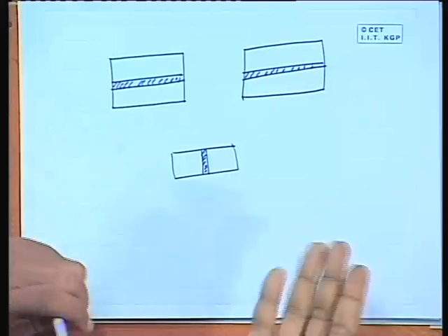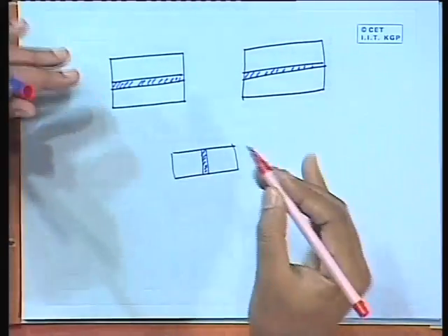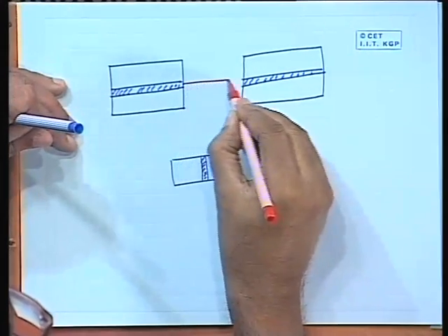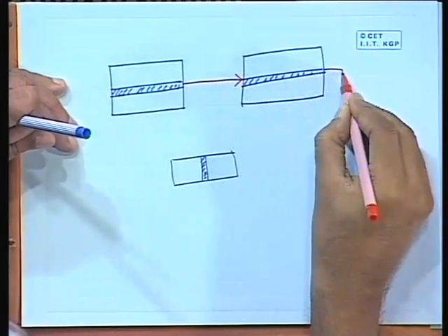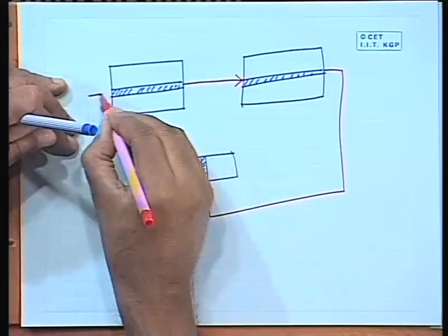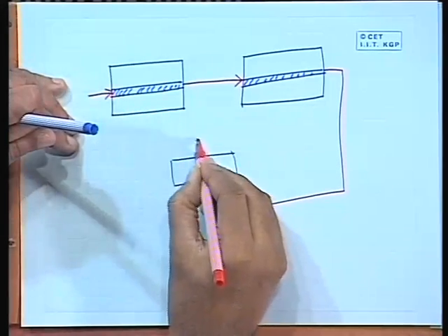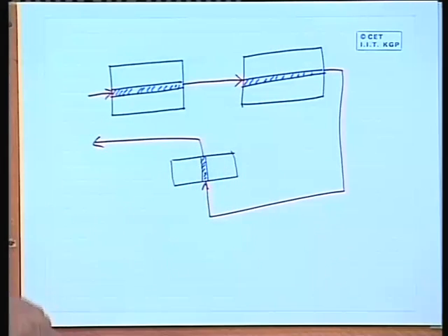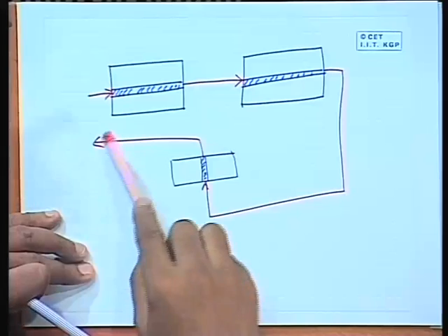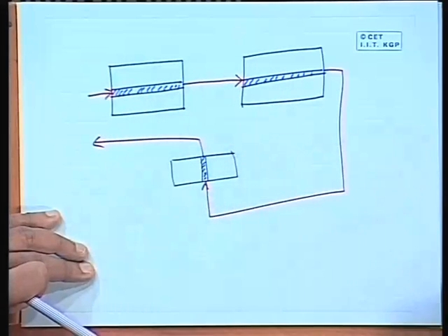Now these modules you are developing hierarchically. Now when you put all of them together on the surface of the silicon and try to interconnect them, you can also integrate the scan paths. So now this will be your scan in and this will be your scan out. So instead of considering the whole circuit together and doing it, you can do it individually.